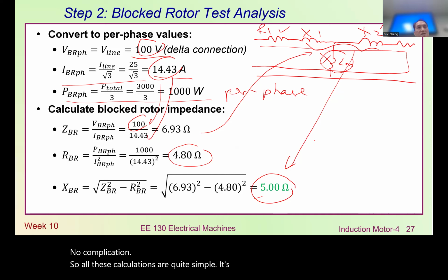So that's why in the last part here, we are using the per phase loss in the no-load test, and then we minus the conduction loss due to the R1. Then the remaining must be the core loss. So you can use this method to estimate the equivalent core loss resistance. That will be this one, right? Lm, then Rc. So that's equivalent.